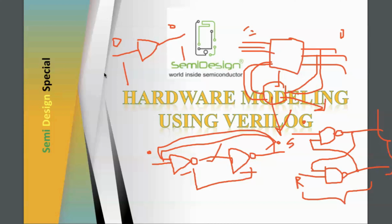Because if we have to design a counter, we simply provide the output of a T flip-flop to the next T flip-flop's clock, whereas in using D flip-flop, we have to make a circuit, and there will be additional components to make a counter.